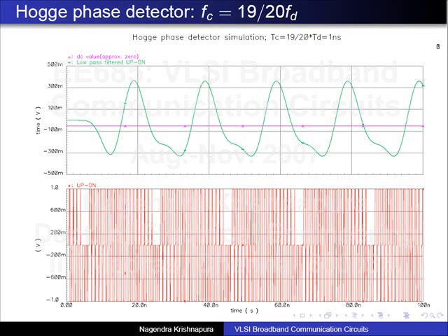So this is similar to the multiplier case that we discussed. The average output is 0, but there is a difference frequency component. So in this case, what will happen is if you put this in a loop, the positive parts will tend to get fatter and the negative parts will tend to get thinner, and then it will capture, hopefully. Okay.